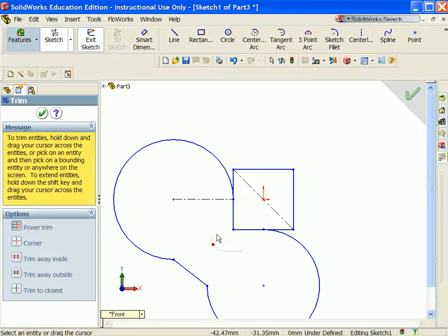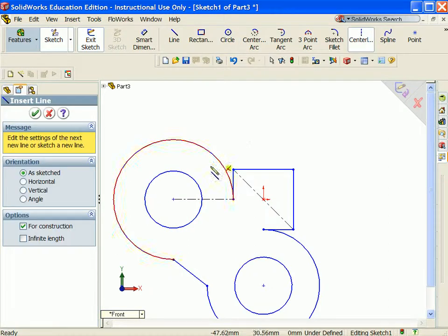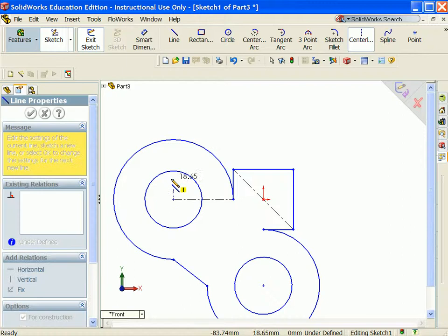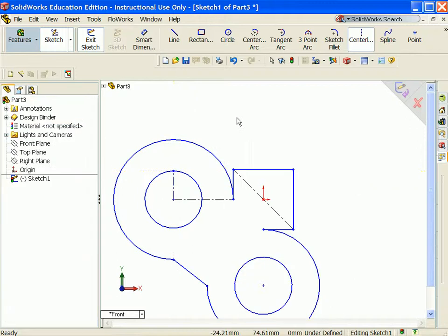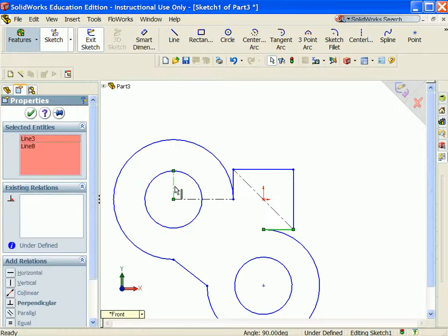Utilize the Trim Sketch tool to remove the unwanted geometry. Sketch a second circle located concentric. Again, I will use a center line to define the radius relative to a linear line segment in my sketch. If it is the design intent for the small line segment of the square and the radius of the circle to be equal, then build that intent into the original sketch with construction lines.